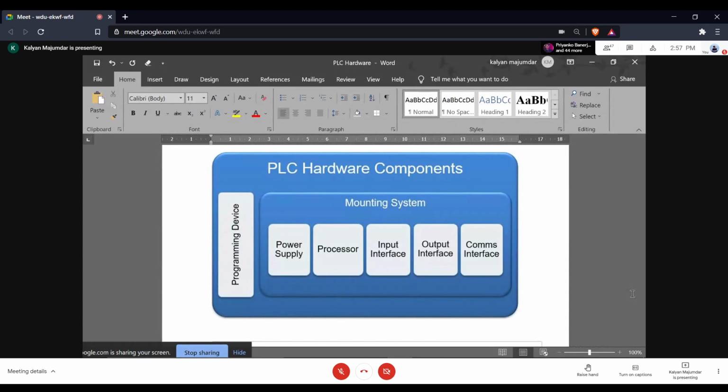So you want to download this particular program, so there is a requirement that you connect your PLC to this laptop which is running Codesys. So any PLC requires a user program, and that user program is always developed in a Codesys-like environment, running either on a laptop or on a desktop computer. This laptop or desktop computer running Codesys or similar programs is what is called a programmer. Why programmer? Because that is where you're developing the user program that is going to run on the PLC, right?